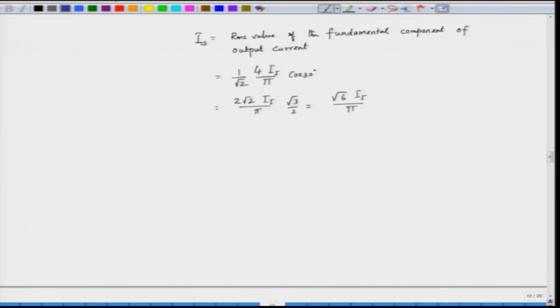So, if we apply this principle to the induction motor, we can draw the equivalent circuit of the induction motor. We have the stator resistance and reactance, then rotor reactance and the rotor resistance here. So, this is our equivalent circuit of induction motor, and we place our magnetizing branch here. So, we do not approximate, we draw somewhat exact equivalent circuit. The losses are included in the output.